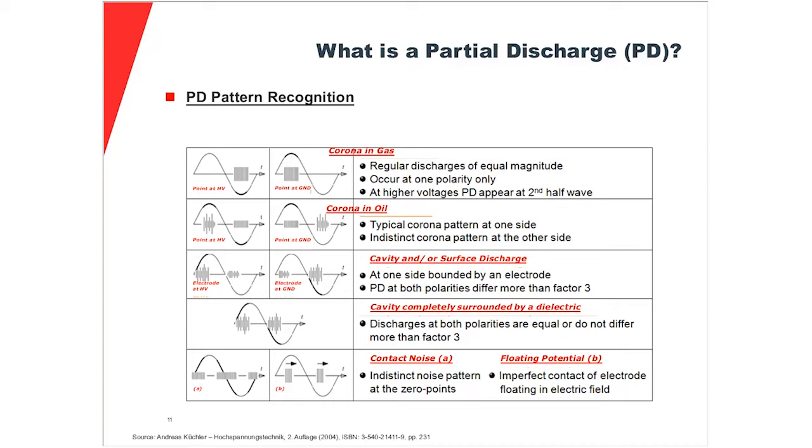To make it short, or to wrap this up, with this phase resolved PD pattern, we are able to identify the cause of the problem, because each partial discharge will draw a different PD pattern, and with this PD pattern it gives us a pretty good idea about the potential defect or the possible cause of this partial discharge problem.